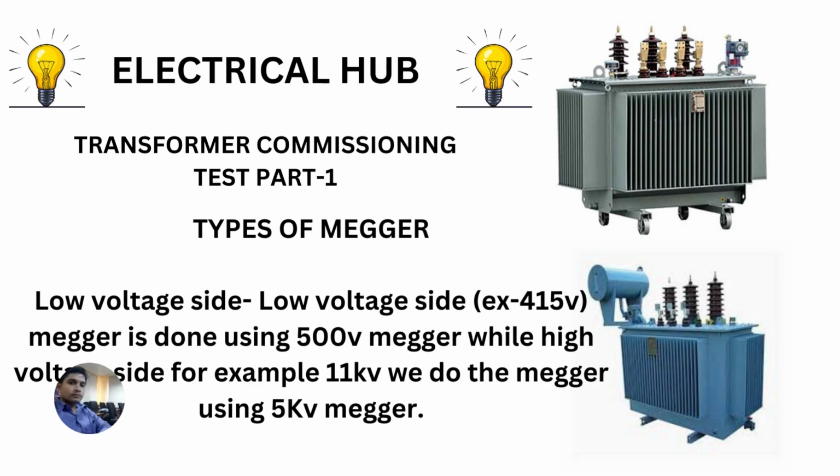For example, here we have taken the LT side as 415 volt. So there we will use a 500 volt megger, while for the HT side, if it is 11 kV or higher than that, we can use a 5 kV megger. Now, for example, if a transformer is 132 kV by 11 kV, then we can use a 5 kV meter for both sides.